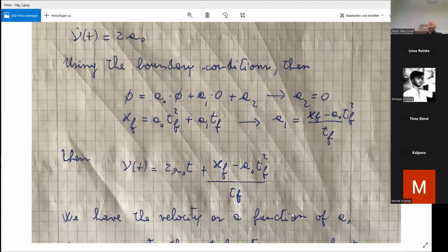Why that? Because mathematically, we need just one parameter to optimize the trajectory. But if I put more than one condition, I will fix A0. But if I fix A0, what is the optimization? It's fixed. This means the original problem can be solved, but I have to consider a polynomial of higher order. It's easy to see, with a polynomial of the second order, I can fix just two conditions, position Lüneburg and position Hanover. And then with the free element which I have, A0 in this case, but could be also A1, we have nevertheless a free element. This can be used to optimize. If I desire more conditions, of course, I have to increase the order of the polynomial.